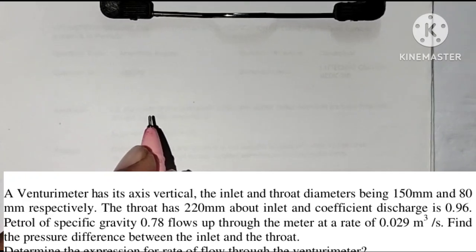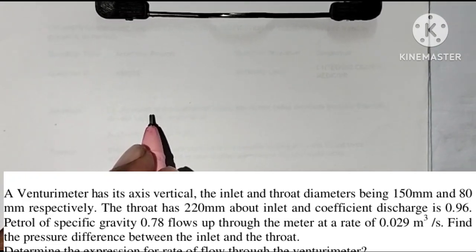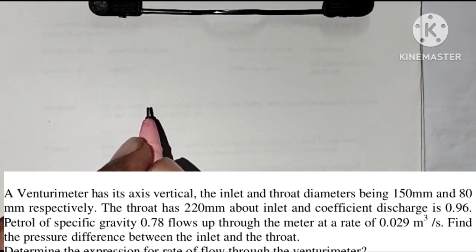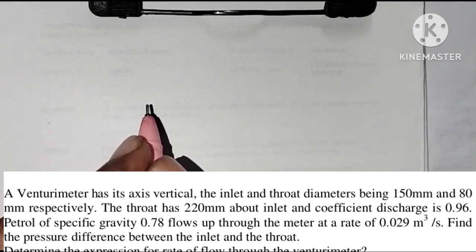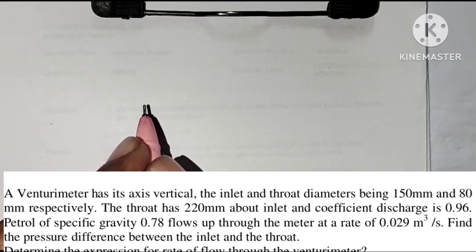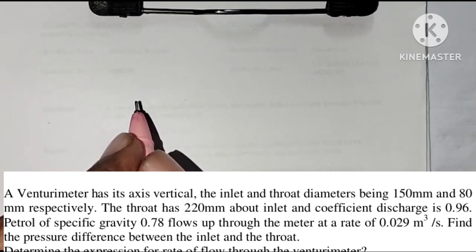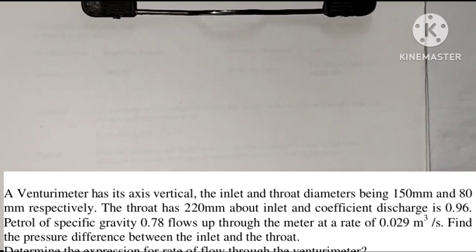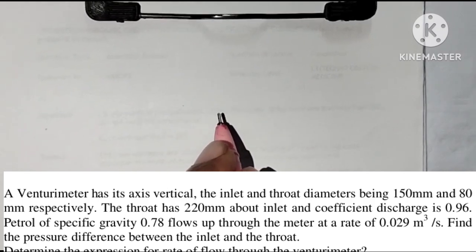A venturimeter has its axis vertical, the inlet and throat diameters being 150 mm and 80 mm respectively. The throat is 220 mm above inlet and the coefficient of discharge is 0.96. Petrol of specific gravity 0.78 flows up through the venturimeter at a rate of 0.029 meter cube per second. Find the pressure head or pressure difference between the inlet and the throat.